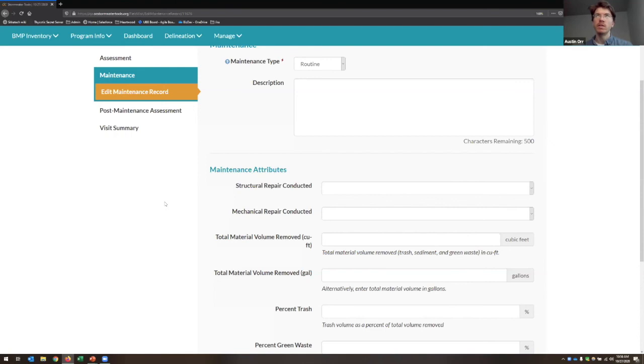And using either a design drawdown time or an underlying infiltration rate, we can use those two data points to enter our functional nomograph curve, which was derived by doing thousands of runs of BMPs of various size, so that we can come up with a long-term estimate of how much volume, over like a 30-year period, that BMP will be expected to capture.